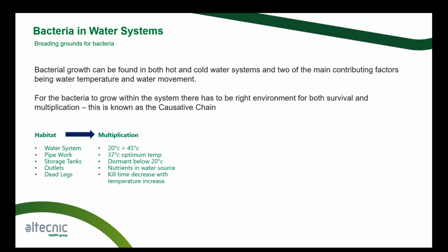Now, the bacterial growth, certainly Legionella, will lie dormant below 20 degrees, but it will still be there. Just because you've dropped the temperature, you're not going to kill off the bacterial growth, it will just remain dormant in the system. Nutrients in the water source, so if you've got algae, slime, or any other nutrient sources for the bacterial growth in the system, it's going to be an absolute breeding ground for the bacteria to start to grow.